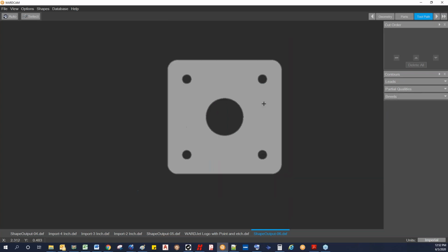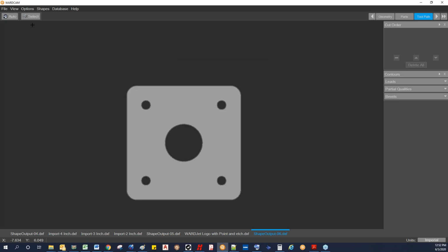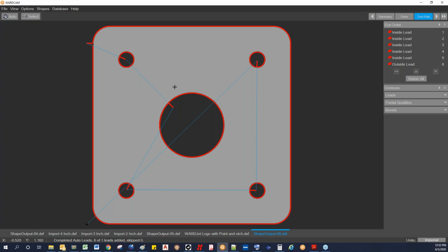In order to add any bevels, first you have to add a toolpath to your parts. So I'm just gonna click on the auto button here to add vertical cuts. If I want to do a countersink on these inside holes, I can activate my Bevels tool, and you can choose from either a top or bottom bevel. As I click on those and change them, it'll show you what it'll be doing. Then you set the angle of your bevel cuts, and how deep down into the part you want that to go. By default, it starts out at 1/2 of whatever your material thickness is.